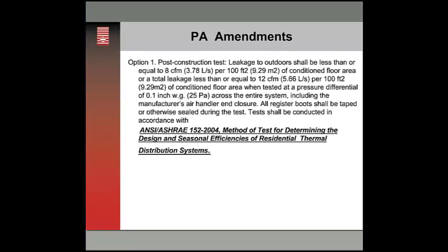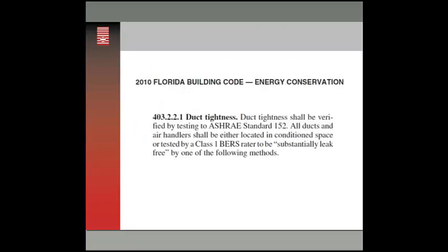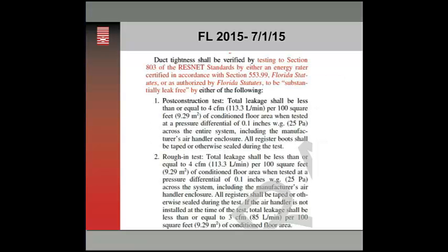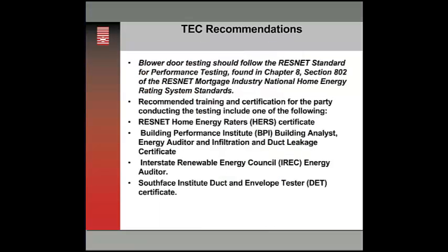Again, some of the other amendments that we've seen out there, back to Pennsylvania, them citing a duct test standard, and actually some new language that's going into play in Florida. Florida was citing an ASHRAE standard 152 for duct testing, and apparently this year, July, Florida will be adopting some of these new provisions for duct leakage, and they've actually cited the ResNet test standard. And boy, personally, that's really where we'd like to see these things go.